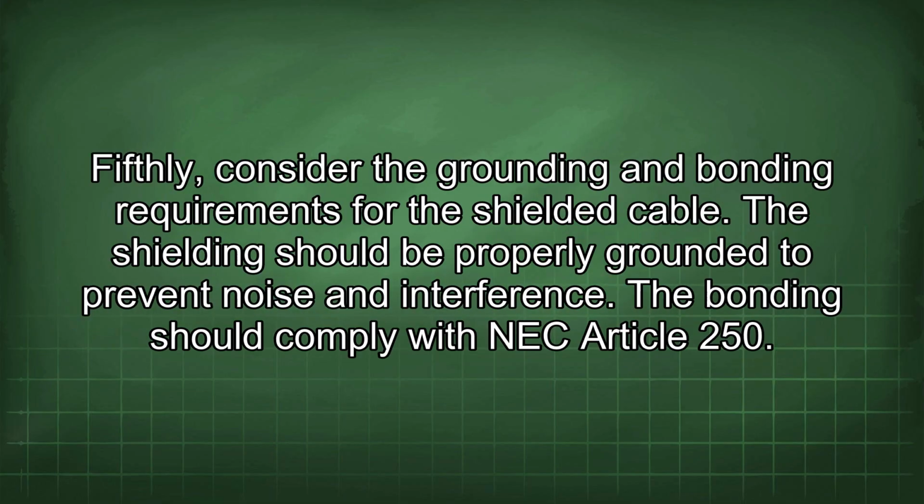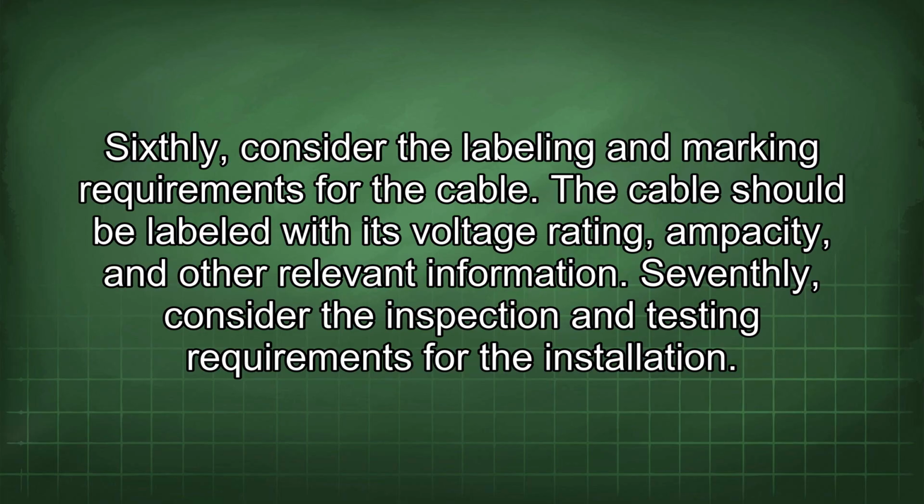Fifthly, consider the grounding and bonding requirements for the shielded cable. The shielding should be properly grounded to prevent noise and interference. The bonding should comply with NEC Article 250. Sixthly, consider the labeling and marking requirements for the cable. The cable should be labeled with its voltage rating, ampacity, and other relevant information.